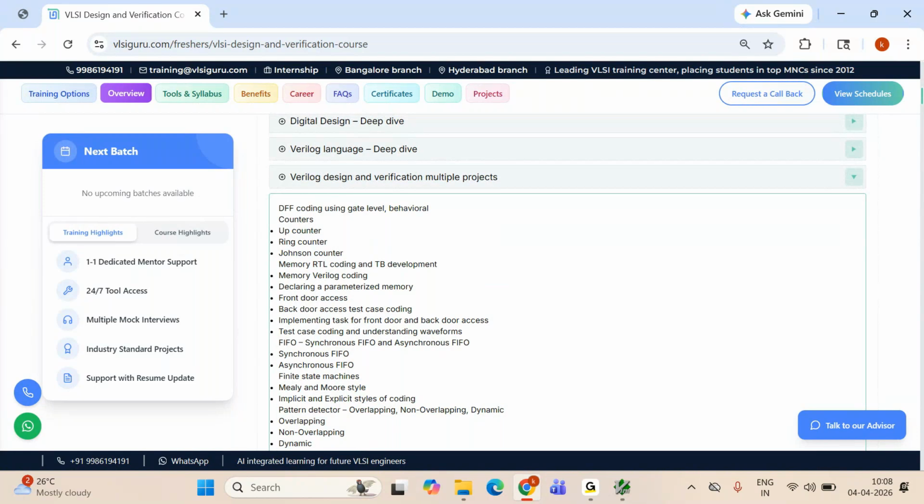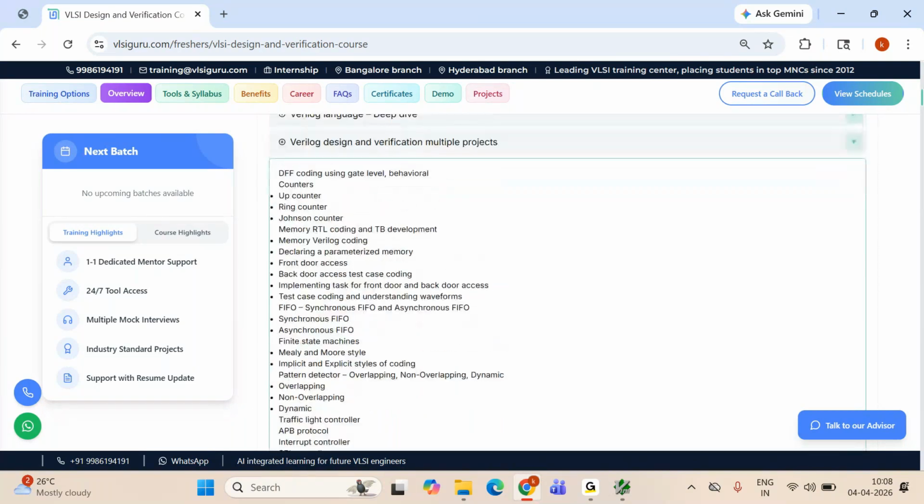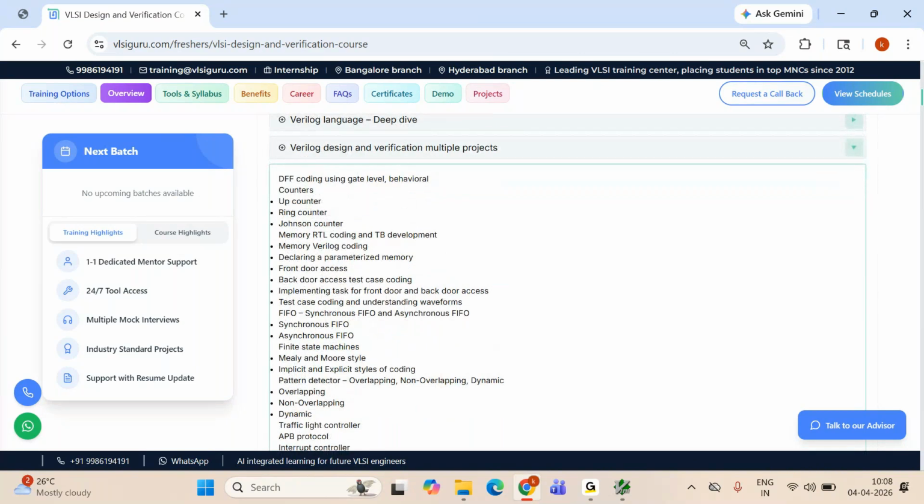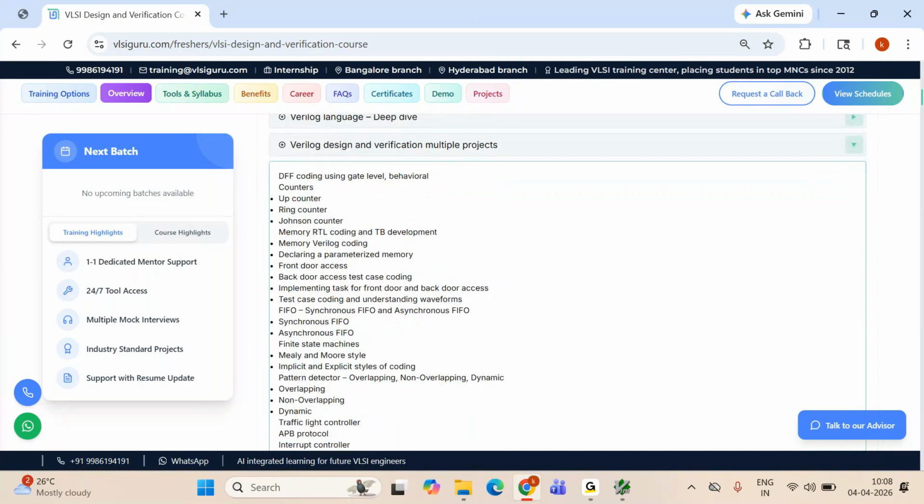You'll be understanding different frequencies of clocks and how to generate them. See, in hardware, clocks are generated with respect to a crystal oscillator. That is different. But when you come to the verification aspect, the clocks will still be generated internally. So how to generate this clock is what we'll be understanding in the first Verilog project, that is the D flip-flop.